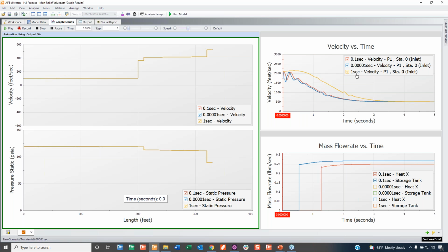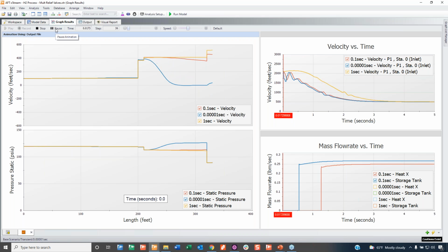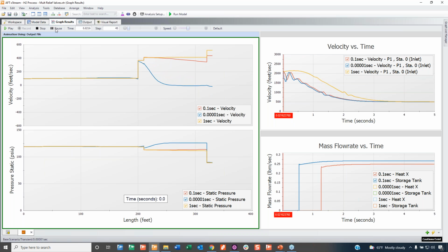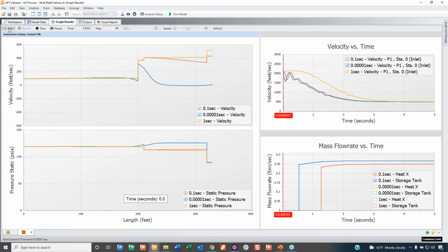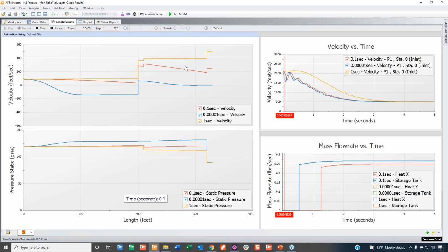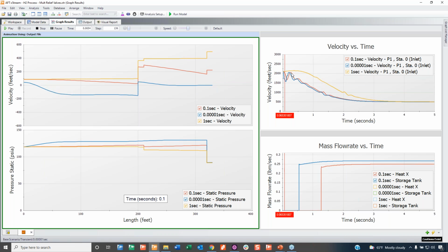closure, where there wasn't really an obvious wavefront, an obvious sudden surge, actually increases with velocity or increases with time and then will drop down. It doesn't have this wave-like behavior. And that's a direct result of the pressure wave and the velocity changes just not being as dramatic. The system has time to settle out. The system has time to correct things without overshoot and overcorrection, right? It just kind of happens. You're changing velocity a little bit. This is an example of a slow transient, right? Where you don't have a huge pressure wave propagation. But it's still interesting that velocity increases, and in no other scenario does that happen.